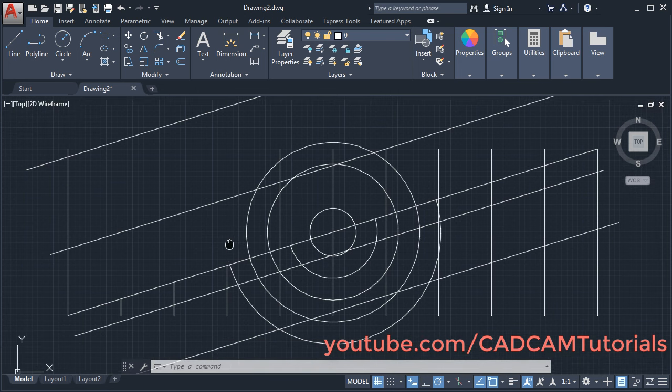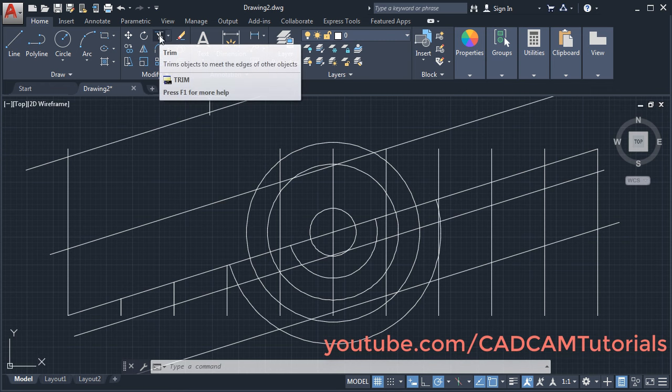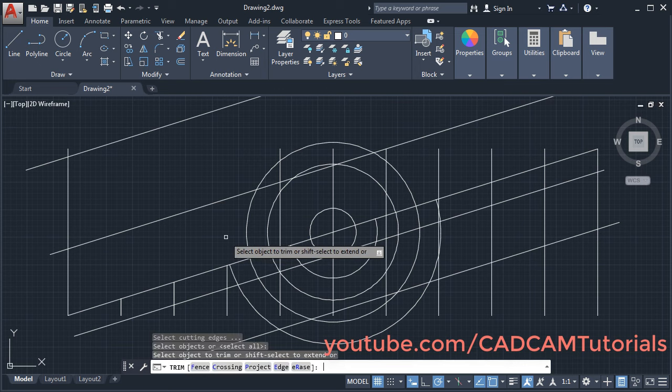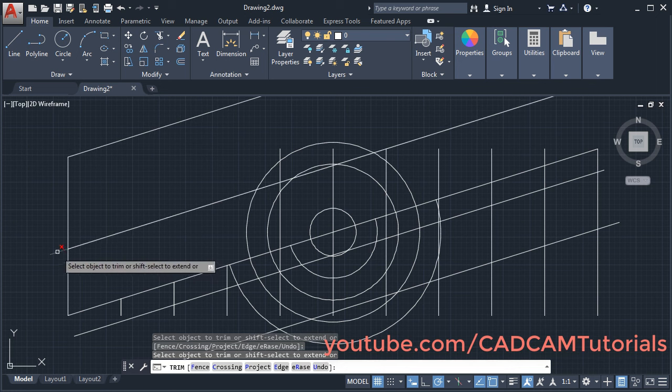Then you can also define all objects as cutting edges. For that, click on trim. Then to define all objects as cutting edges, you will have to press enter. Just press enter, so all objects will be defined as cutting edges. Then you can remove any object. Just click on the object you want to remove, so that object will be trimmed.